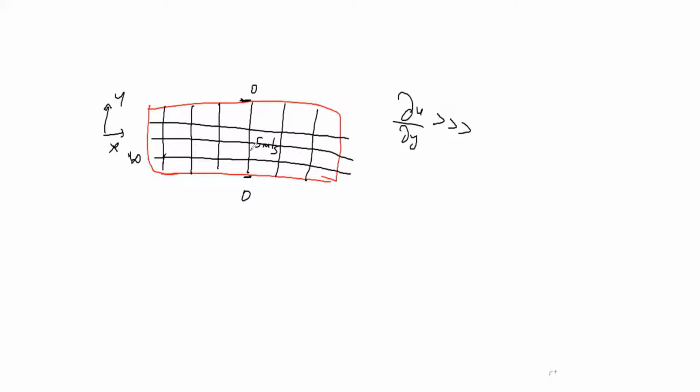Yes, sir. So I want to basically see at any random location how the velocity is changing at this probe. So I will create a probe in ParaView or the Insight, which is a post-processing tool. I am interested in the X component, right? Because velocity has X, Y, Z components. So I'm interested in this component, which is nothing but the X component of velocity. Here it is 0, here it is 0, here it is the X component. And basically I am getting this parabolic profile. This is the X component of velocity.